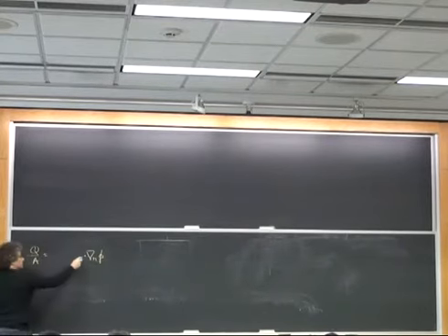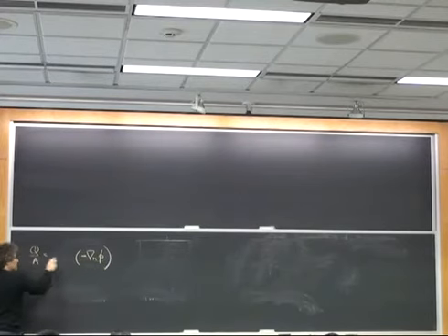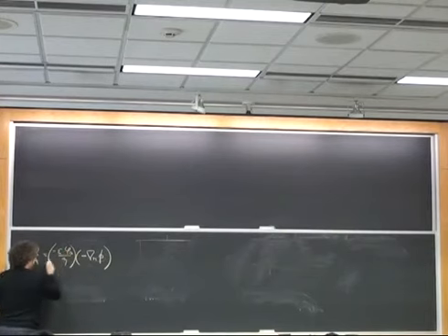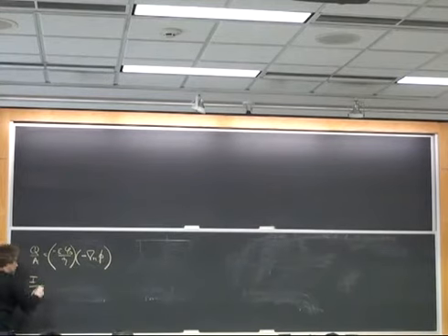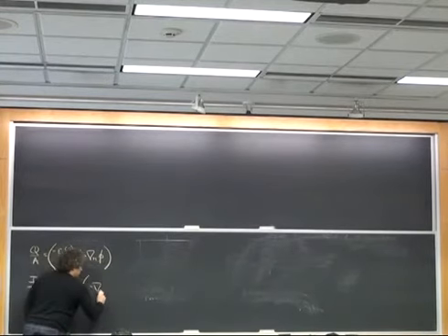So just as we could say that the average velocity, or volumetric flux normalized by cross-sectional area, that we induced by an electric field, just as the proportionality constant for this was given by minus epsilon times phi naught over eta, we also could say that when we go to measure the net current density that's generated by a gradient in pressure, the proportionality constant here is also given by epsilon phi naught over eta.